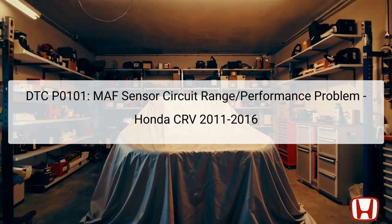The MAF sensor is typically located near the air intake manifold, connected to the intake air duct. If this sensor is malfunctioning, it can lead to various engine performance issues and affect how the vehicle operates. After confirming the DTC, it is essential to cross-check for other related codes to ensure a comprehensive diagnostic approach. Always note any freeze frame data that can provide insights into the conditions under which the error occurred.